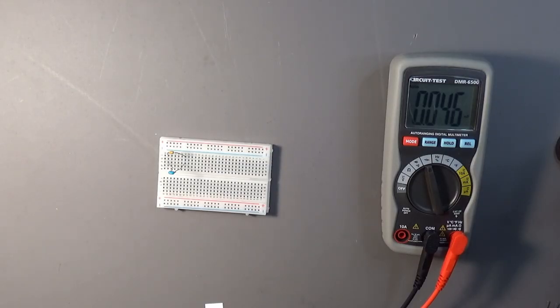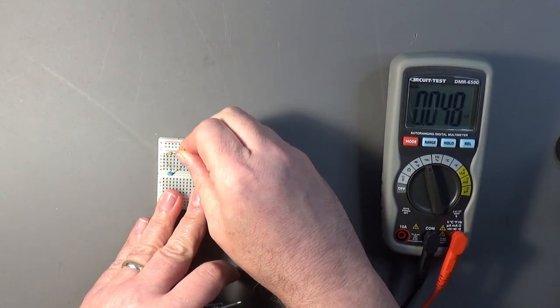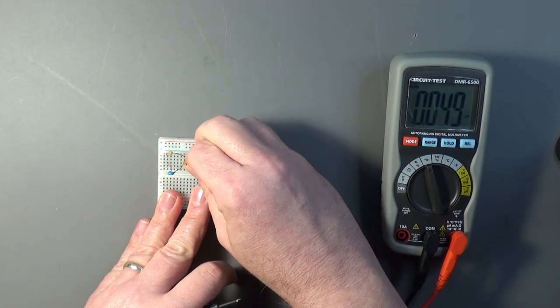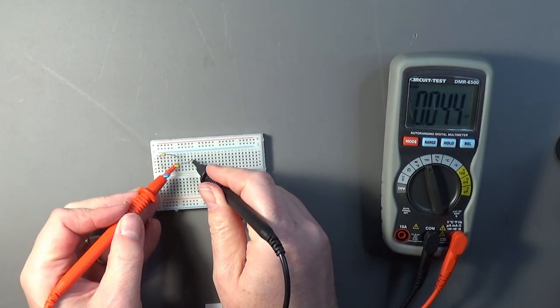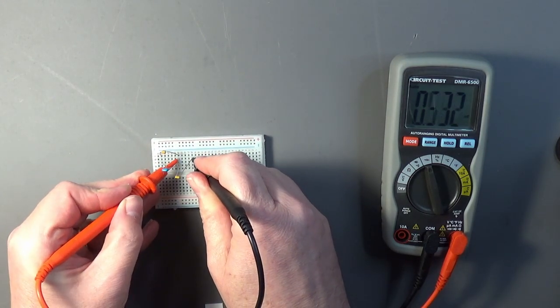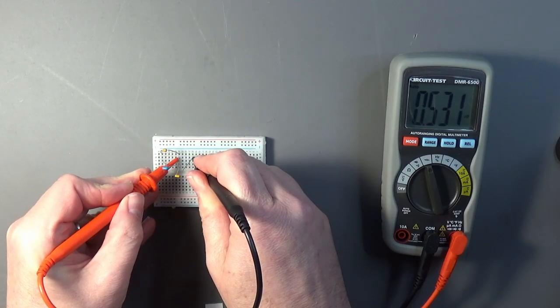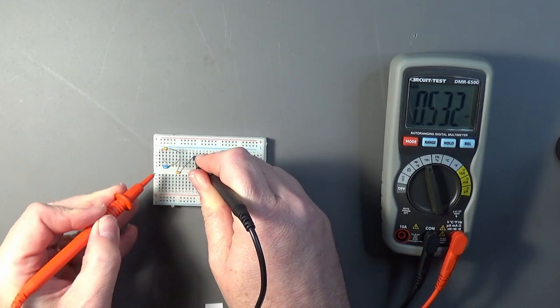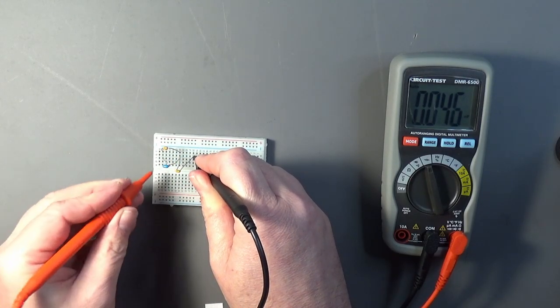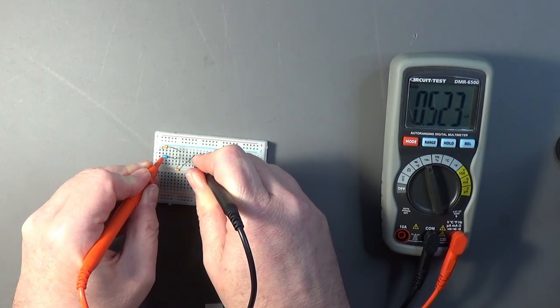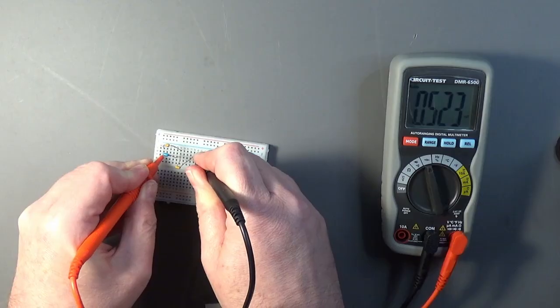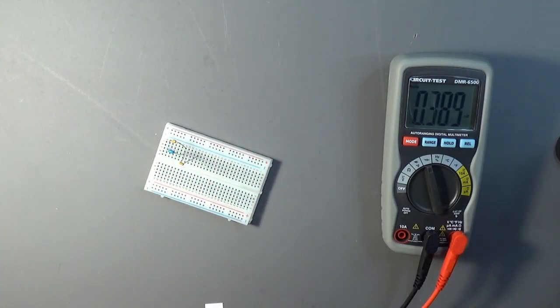To show that this actually works even further along, take this guy in here, plug this guy in here, and this guy looks like about half a nanofarad, or 530 picofarads, and now he's in series with this parallel thing, which is about 25, and we end up with about 0.52 nanofarads for the whole thing. So you can see how that works out.